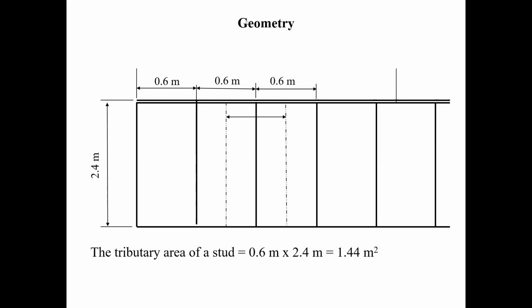Okay, now, this was our geometry. The reason we need our geometry is that when we're looking at wind loads, the coefficients that we're looking for come from a different table when you're looking at cladding. They're not the same ones that you saw in structural analysis, because structural analysis was for the primary frame of the building. That's what you did the wind loads for.